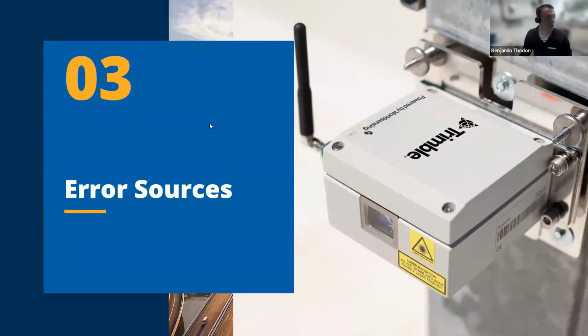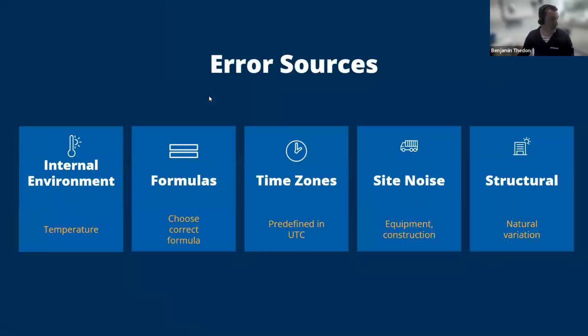Now we're going to talk about the error source in geotechnical monitoring. So we have different sources of error. First of all is the internal environment. This is why we have a temperature sensor inside the device to be able to monitor the temperature and correct the tilt sensor value with the temperature.